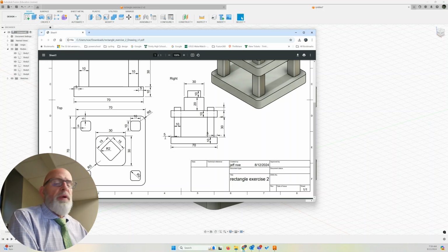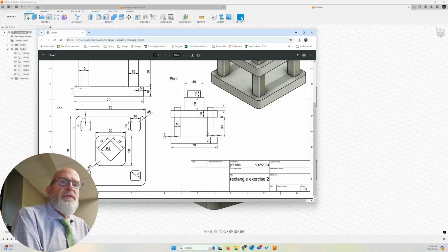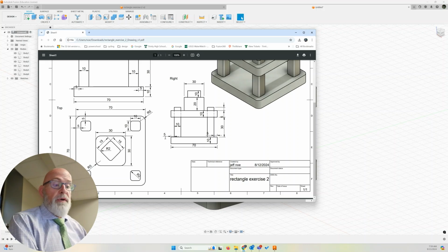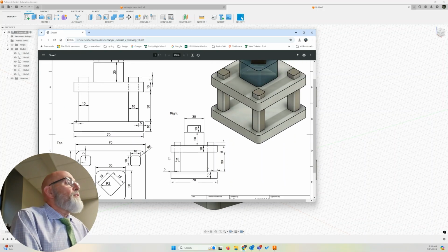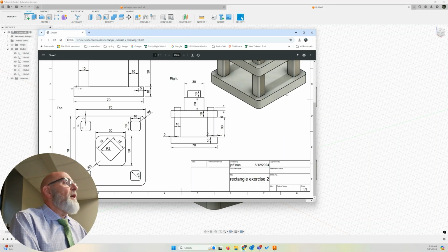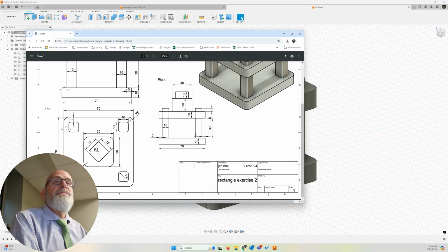And you know what I think I missed on the first video when I was toggling the construction lines to construction? I was using the X key to toggle them back and forth. I use the X key more than flipping construction on in the palette, because I always forget to turn construction off when I go to draw my next shape. So I just use the X tool to toggle things back and forth. So we'll do that, and I'll demonstrate that.